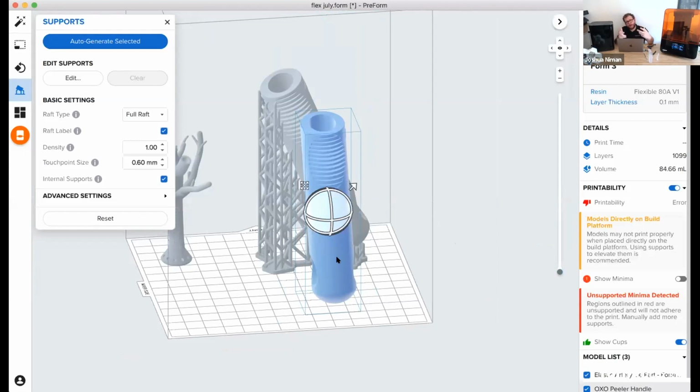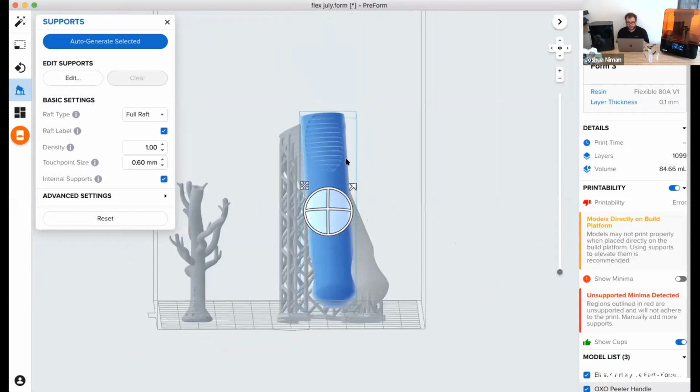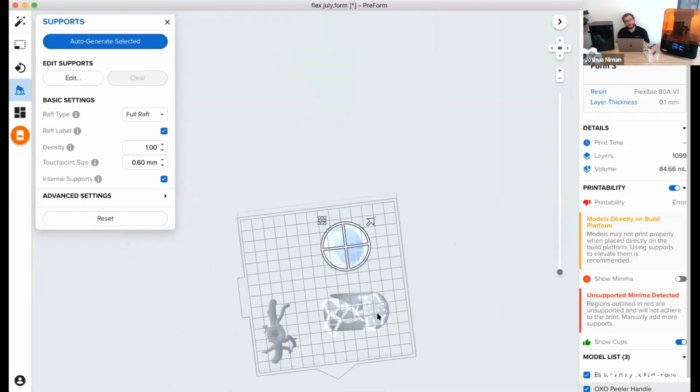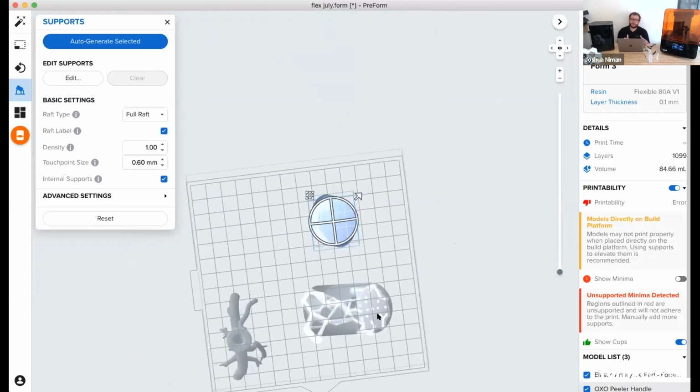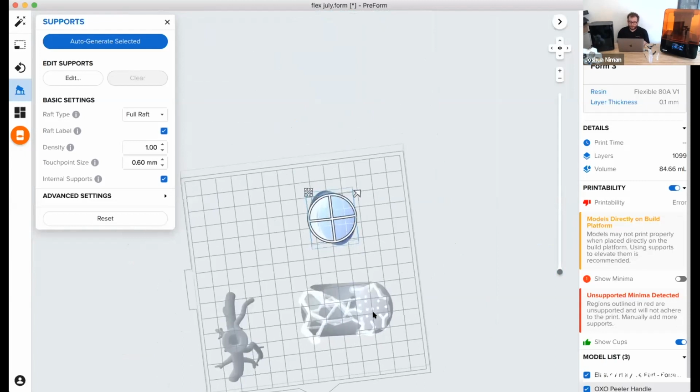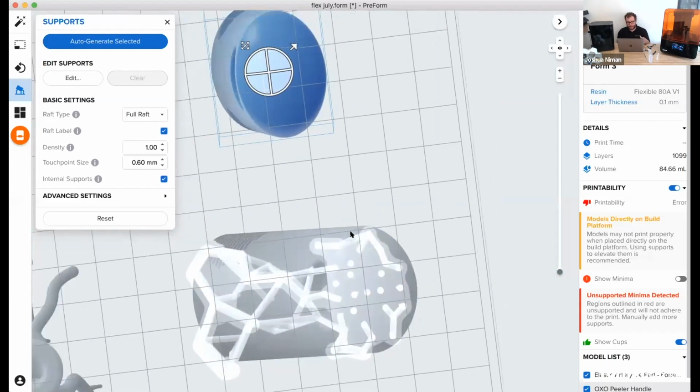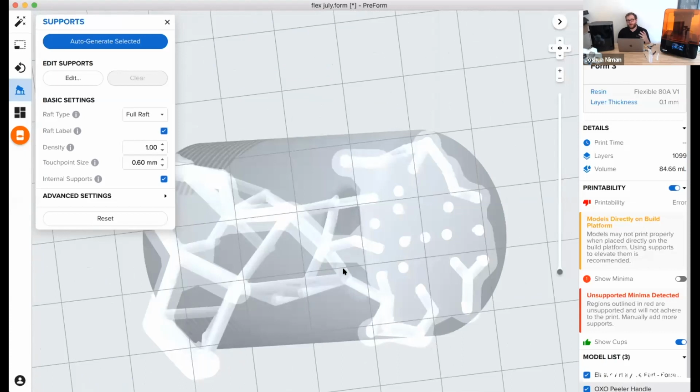And the smaller the base or anchor point of supports that you can put on it. So I always like to think when I'm supporting a part in terms of a tripod, because a tripod is a really stable structure to hold something up, right? And so when I'm orienting, I like to think of, okay, where are the legs of my tripod going to be so that the whole part is relatively stable and hard to shake while it's printing.